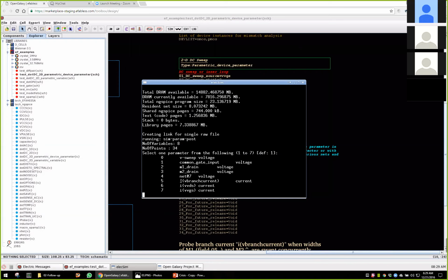And more importantly, I've got branch currents. Where it says current, that's where I have the probe current. Wherever I've placed probes, I'll also have the currents passing through that probe listed back here. So at this stage, I'm just going to quickly plot the probe current.